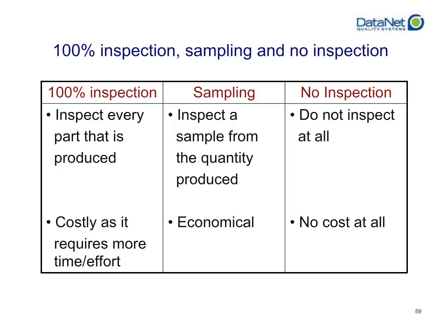So 100% inspection gives you visibility on everything you produce, but it is extremely expensive. The other extreme is no inspection at all. The advantage to that is it's cheap, at least up front. It doesn't cost anything to not look at any of your product that you produce, then you just go ahead and ship whatever you produce. The downside to that is you have absolutely no idea what you're shipping.